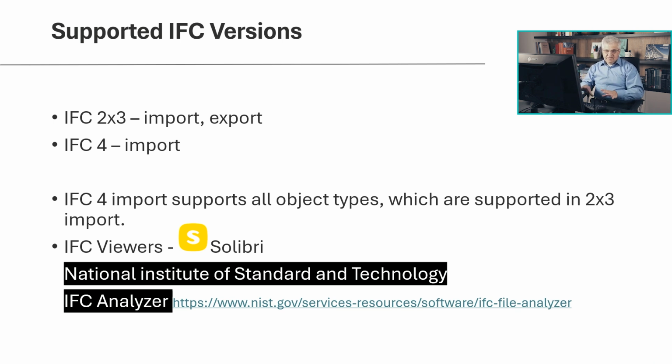Before you import this file, please check it in some viewer. There are a lot of viewers. They are free. You don't need to buy them. Nemetschek has one. There is one from Autodesk. There is one from Tekla. I am using the IFC viewer called Solibri, because if there are some issues with this IFC file, I have seen that this is the program which gives me the most information about all these issues and errors.